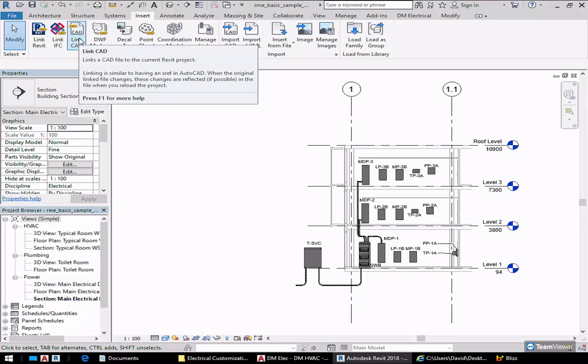But given that I know people are using this in Revit, I'm sure there's a way to have layers mapped to certain line weights, basically, is what you're concerned about when you're actually doing your plotting of the new versus existing, new stuff heavy, the existing stuff light. So I'm pretty sure that there are ways to do that. I would guess there's good Revit tutorials we could look up online. If anyone does need additional help on that, I'm getting an answer. That is controlled with the export to drawing command in Revit. Yeah, so it can be done. It's just going to be a little bit of Revit work to make that happen.